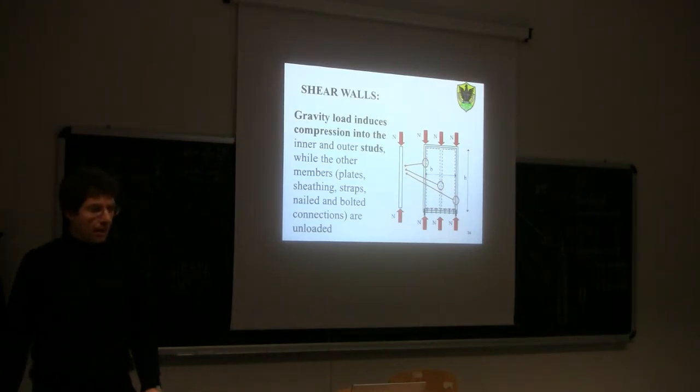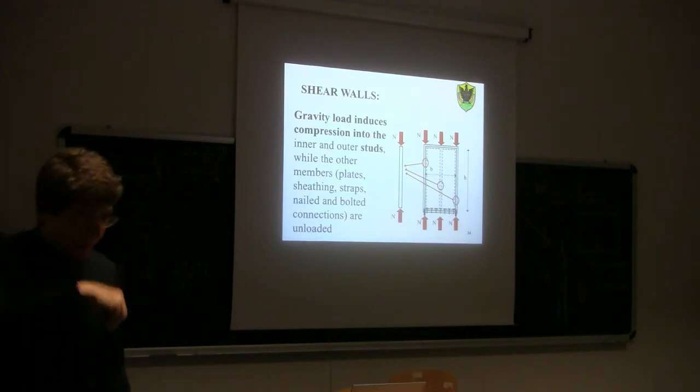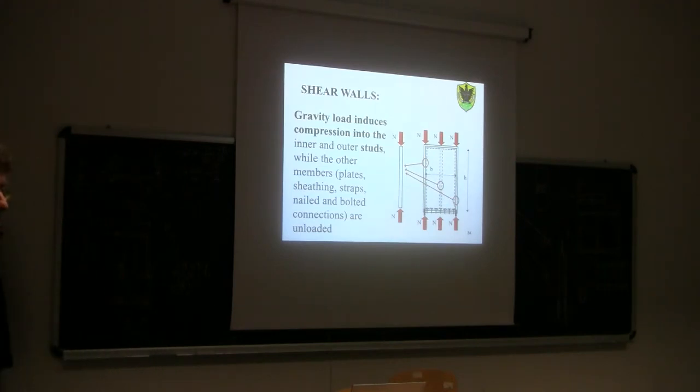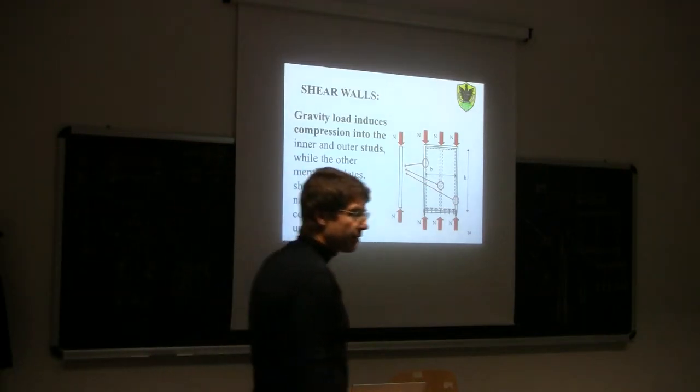Okay? Otherwise, we don't have any way that we can transfer this axial force down to the foundation. Is it clear? So, a metal strap nailed to the stud and then taking this axial force down to the foundation, or down to the other floor, or down to the other wall underneath. Is it clear?